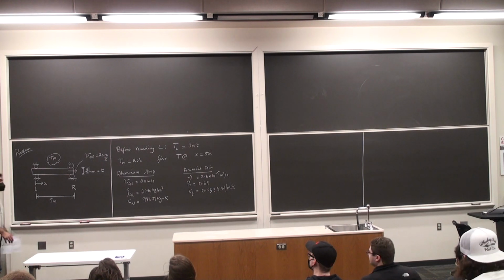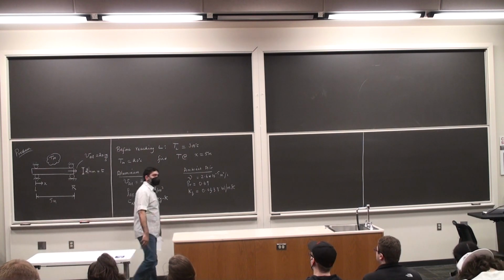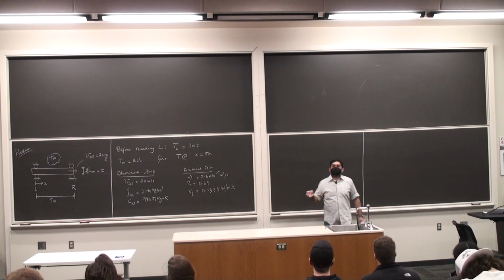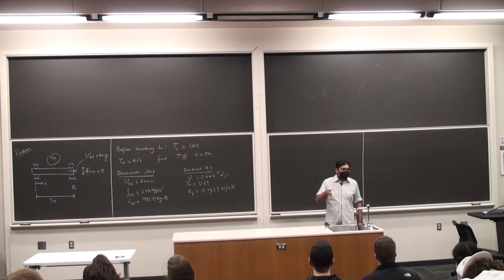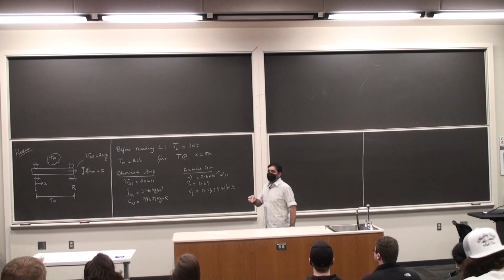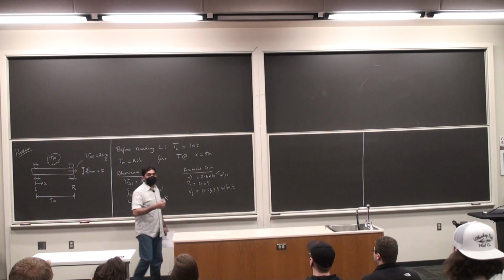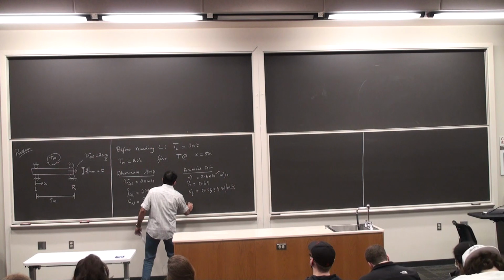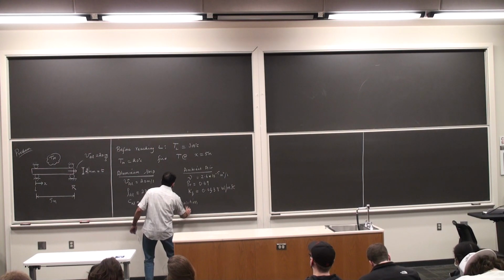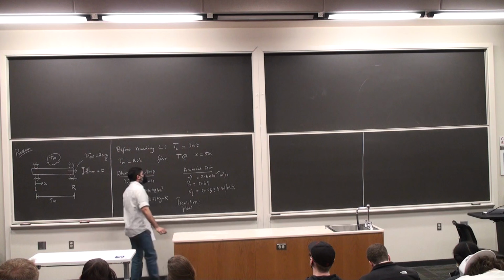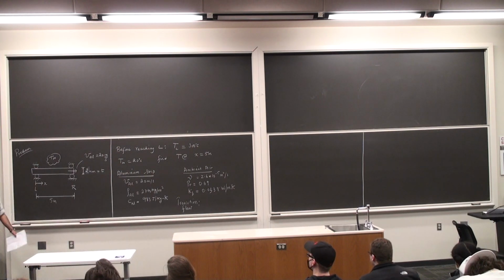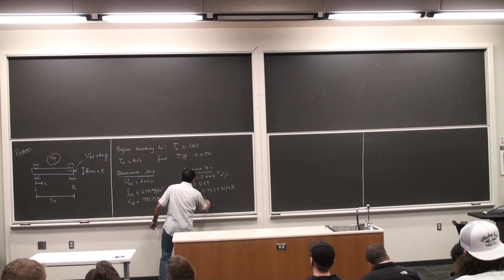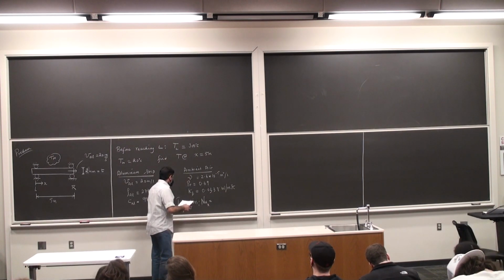You're told that the whole problem, and perhaps this is by design, is performed under a transition regime of the flow conditions. So the Reynolds number is between 5 times 10 to the power 5 and 300 times 10 to the power 5. So this is transition flow, boxed between the laminar and the turbulent regions, and so the Nusselt number is given as follows. NUx is the local Nusselt number.